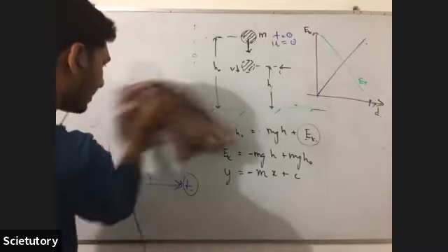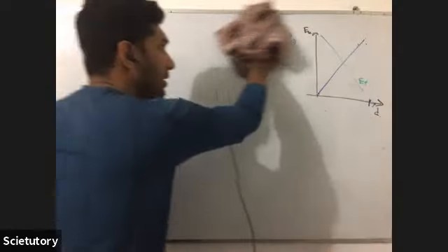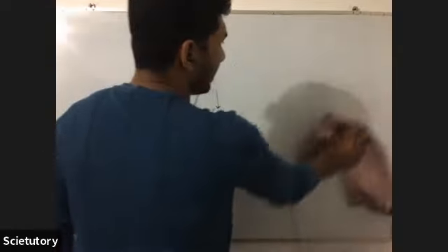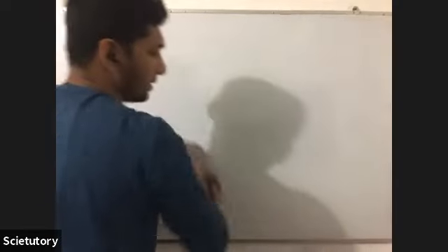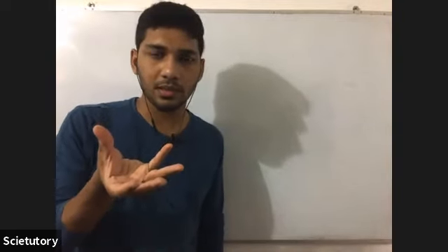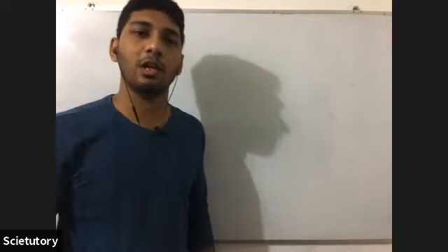So the mass remains the same. According to the law of flotation, the weight of the water that is displaced should be equal to the weight of the object for it to float. So the same volume of water should be displaced. That's the theory. Initially M, now also M, so the same volume of water should be displaced.